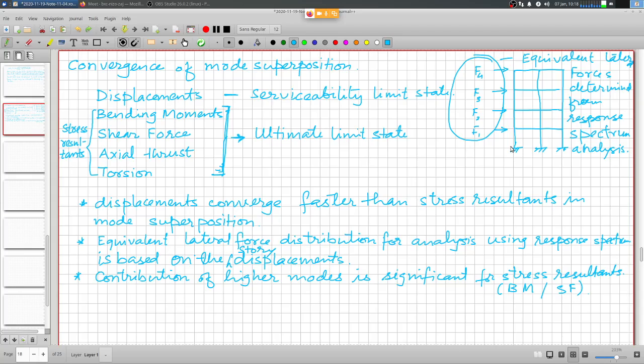Because the upper floors were already designed for lower levels of forces, they had much lower capacity to accommodate this kind of omission. The lower floors, because they were designed for higher capacities, had more cushion to absorb this kind of error of omission, and that's how several upper floor stories sustained heavy damage during the 1985 Mexico earthquake.